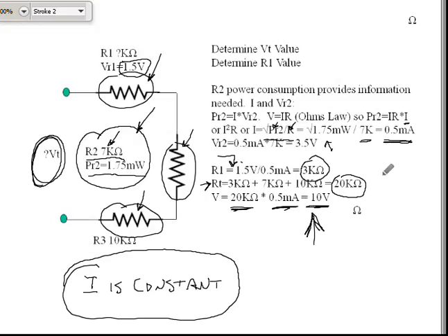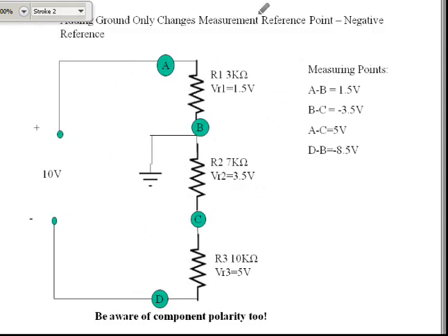So that's playing around with series circuits just a little bit. Of course, we went through all of this last week with the difference in grounds, and how they affect your reading via a meter. This ground point gives you a reference point. If you've got a reference up here, but you're measuring from D to B, the black lead on your meter is going to be higher than the plus lead. If the negative lead is higher than the plus lead, you end up with a negative measurement.